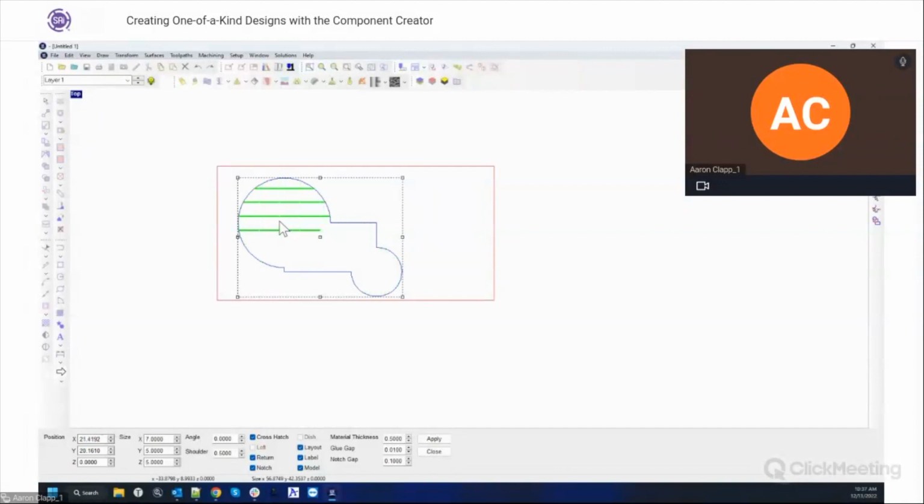I can drag these around if I want to, and you'll see the little red nodes appear. These little red nodes basically mean that there's a conflict point at one of your intersections. So it's not going to be able to create the proper intersection that it needs to create. So you want to adjust it slightly so that no intersection points land on the edge. That's what those are.